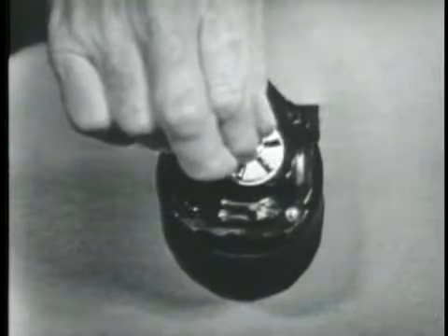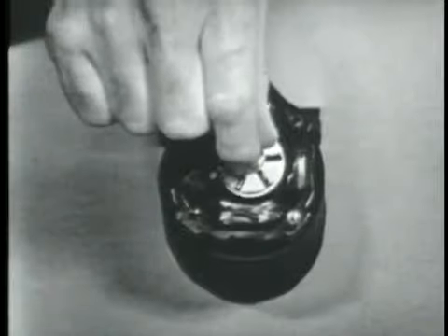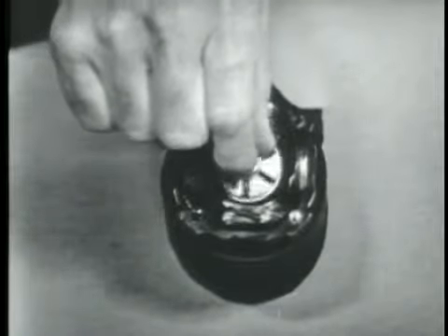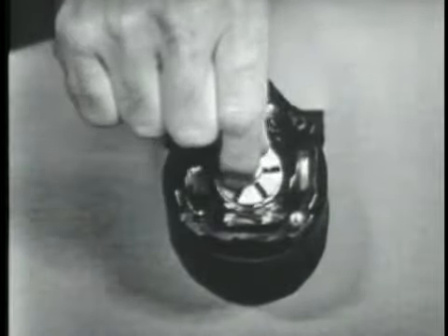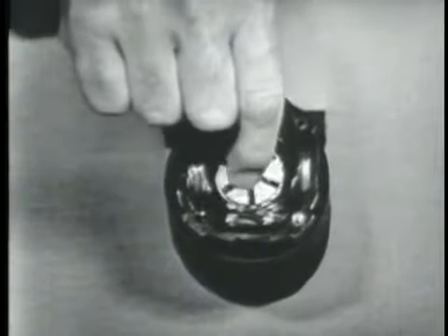Proved, Tom, not really easily, because the magnetic field is attracting the rotor toward the stator. It's kind of hard to get in. We've got it in there now, and if I let go of it, it rotates. Right. And obviously something must be causing it to rotate. And that something is the rotating magnetic field.